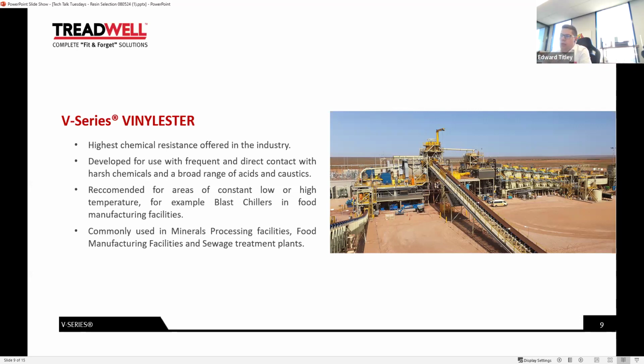So we'd also recommend the V series for use in areas of constant low or high temperature. And we've mentioned blast chillers in food manufacturing, mine roasting equipment, those sort of things. The V series product does better in that environment. It maintains its mechanical properties at higher temperatures and also resists becoming brittle at lower temperatures, which the I series product doesn't do so well in. So something to think about there.